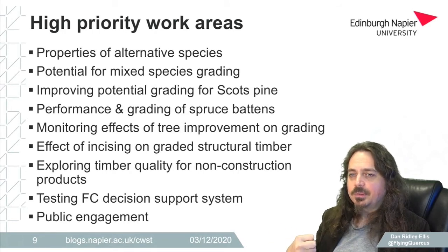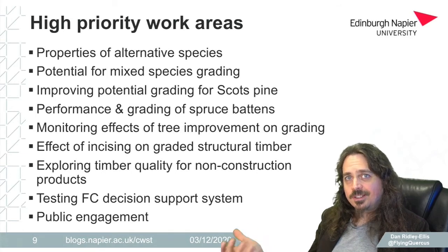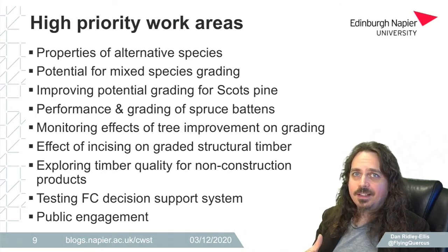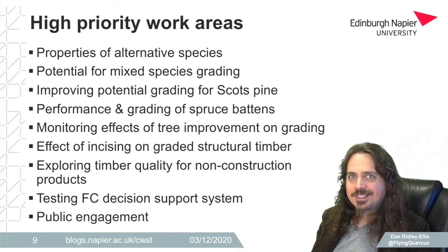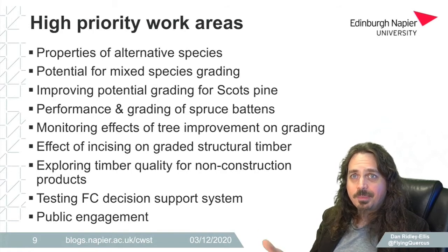So for example, if we're using X-ray machines for the grading, do we have the same correlations between knots and density and strength and stiffness in this new improved material than we had in the past? And because people are getting better at this tree selection and tree breeding program, we think that there is this potential for a change. So that's something that we need to check to make sure isn't happening.